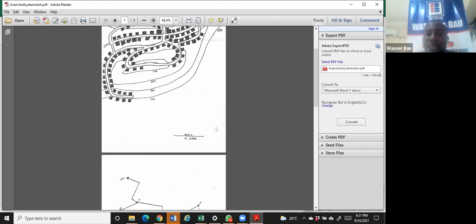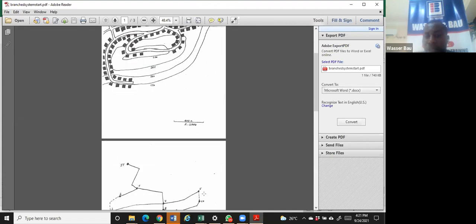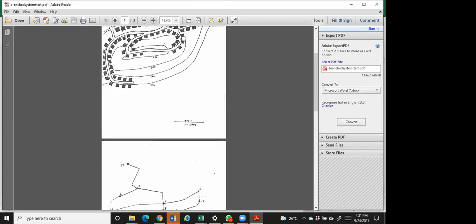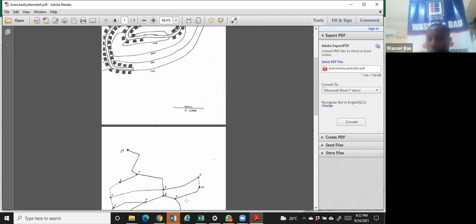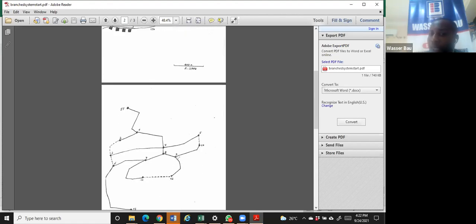So even if you are designing a loop system here, what this simply represents will be a valve. You introduce a valve here, and a valve here, meaning that this valve can be opened in case of maintenance. Assuming I'm maintaining something here, I can open this valve so that people in node 10 can get water through node 5. If not, they are originally supposed to get water from node 9. So water passes through node 4, goes to node 8. At node 8, it divides proportionally into 7 and 9. 9 divides proportionally into 10 and 12.